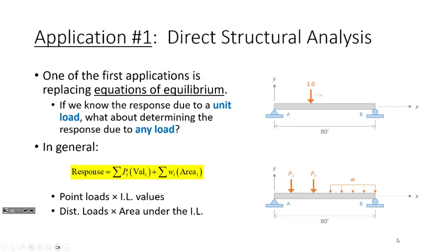You'll understand that a little better on Monday, but long story short, whenever we're looking at real-world loads that we're applying to, let's say, bridges, we're never really applying moving triangular loads on bridges. It doesn't really work like that. Really, the only loads that we're applying that move on bridges are point loads and distributed loads. So for that purpose, influence lines are going to work just fine.